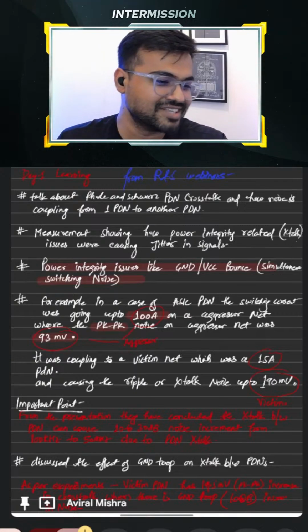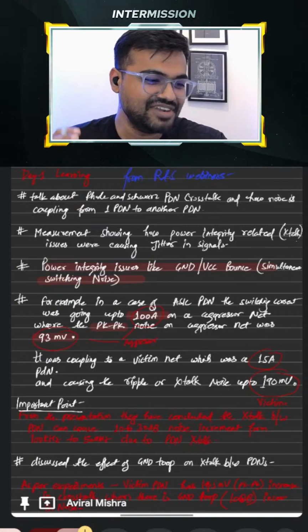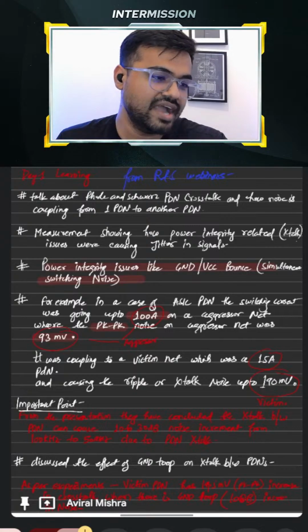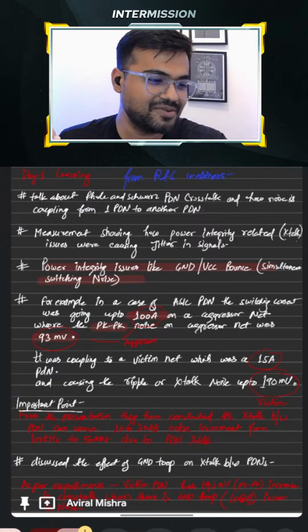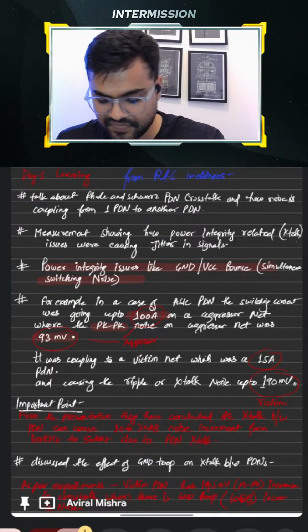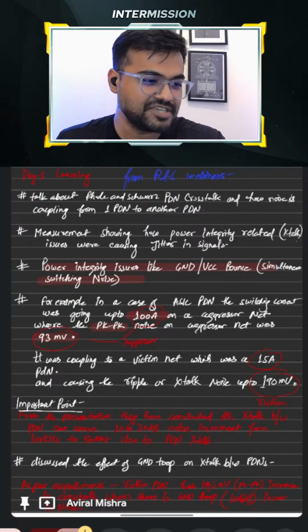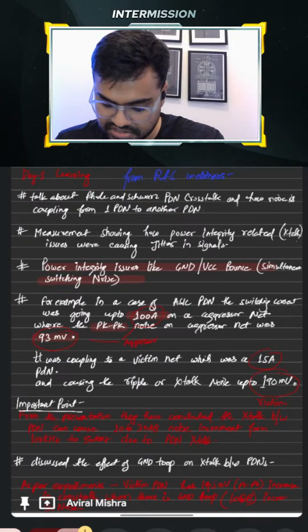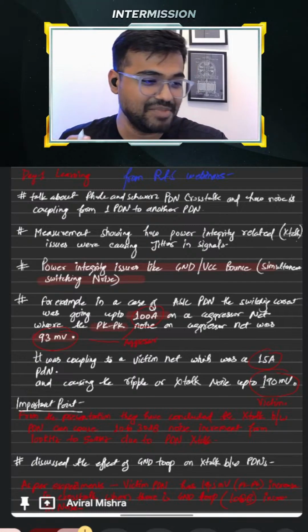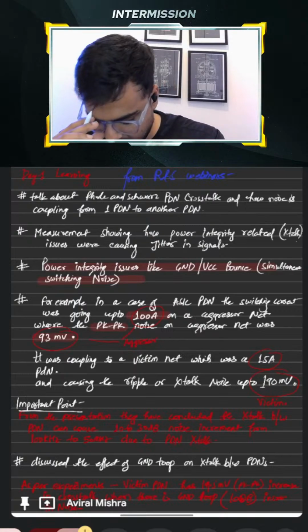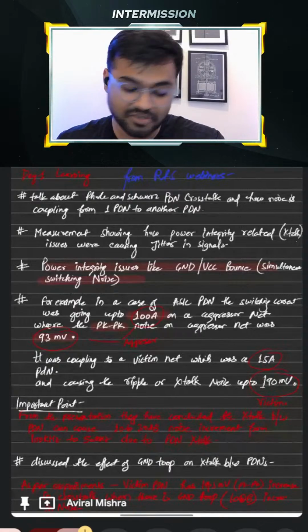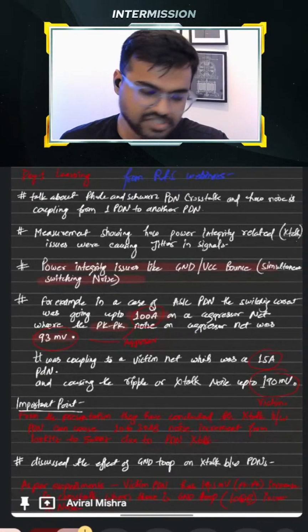So you can imagine the design was so efficient. Even if we just use a 3 amp DC-DC converter, put the oscilloscope into AC mode and measure the ripples, you can see it can exceed that limit, right? So imagine the efficiency of the design they were presenting. It was just 93 millivolt peak to peak noise at 100 amps of current, right?